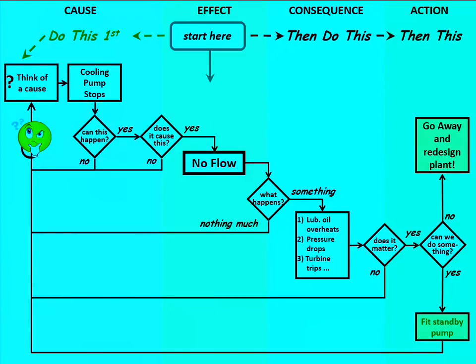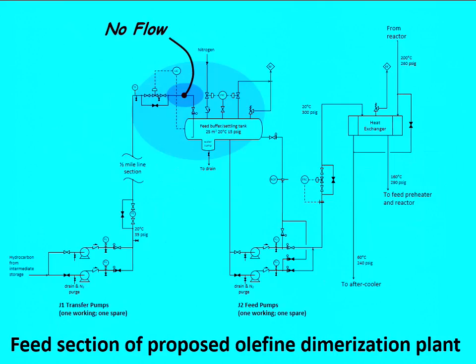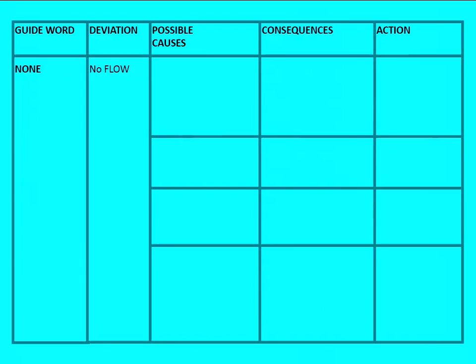So, what does HAZOP benefit? Well, it's really useful during the design or the installation of new plant, or when you've had major modifications, like I've just said. It's useful when there are novel hazards, things that you haven't thought of before, environmental hazards, big on quality or cost issues. If your plant has had a major incident and you've repaired it and you're ready to put it back online, then it's a good idea to carry out a HAZOP on it, because you don't want that sort of thing to happen again.